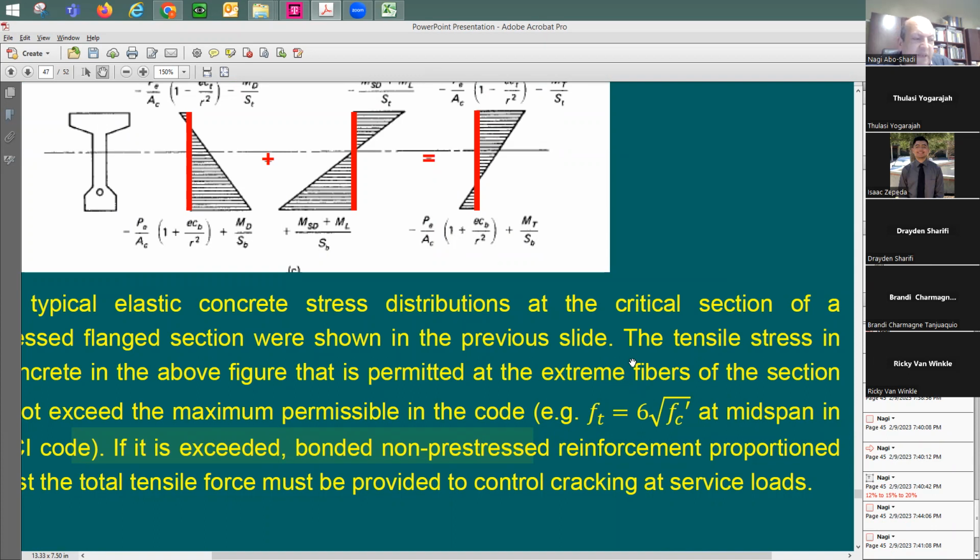In a cast-in-place concrete beam, non-pre-stressed, you cannot do this because you're going to have lots of tensile stresses, and the rebar is going to get triggered and needs to help you support the loading. But in pre-stress, I can control the amount of stress here at the bottom by controlling the amount of pre-stress I'm going to put here. And if I can confirm to you that the tensile stresses at the bottom of the beam wouldn't go beyond this limit, it means I can have a beam free from cracks. I can do it. You can just play with the numbers.